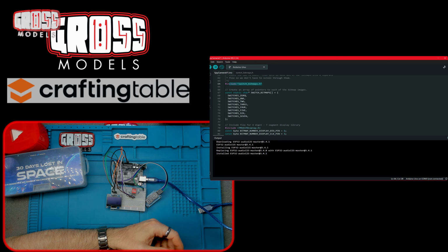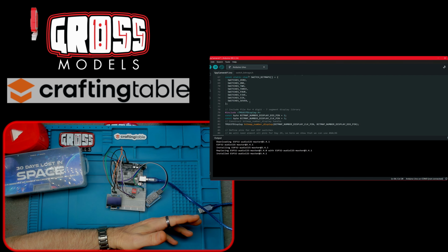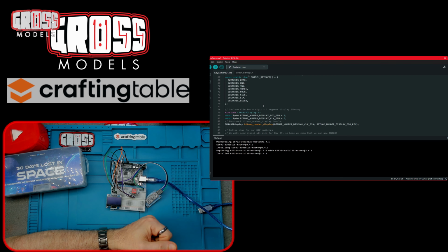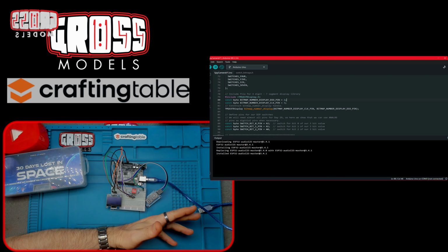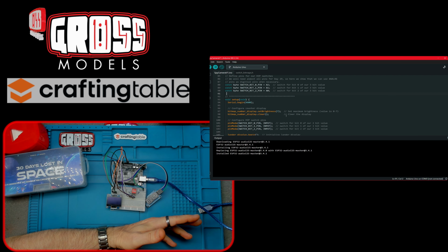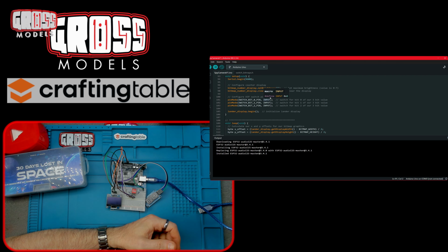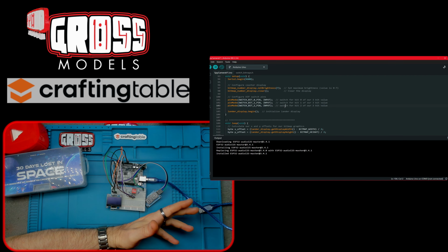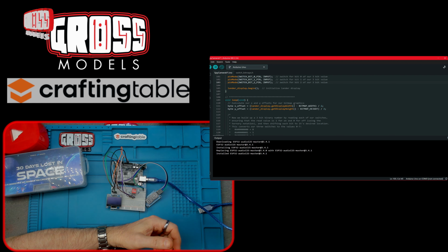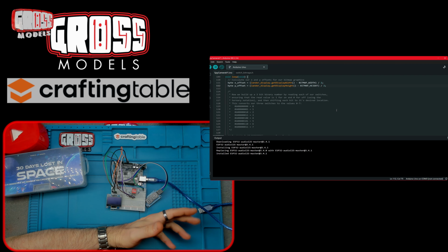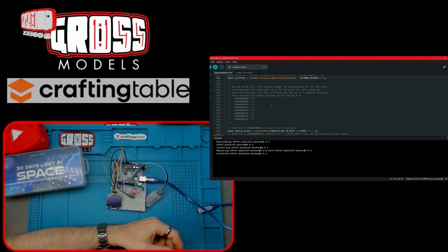So we've got a figure here. The array of pointers, depending on where the switches are, 0, 1, 2, 3, 4, 5, 6, and 7, tells us where to switch the bitmaps to. Okay. So we're setting the bitmap display number, pins, we're telling it where the switches are. Then we're starting up. We're just telling it that the pins are inputs, obviously. And we're calculating our X and Y offsets for bitmap graphics, telling it just where the bitmap displays are and things. Build a 3-bit binary number by reading each of our switches.